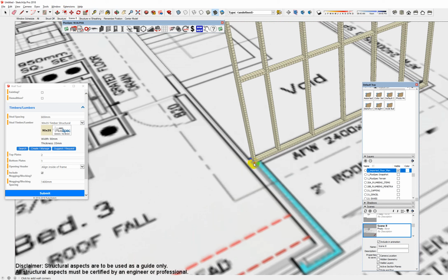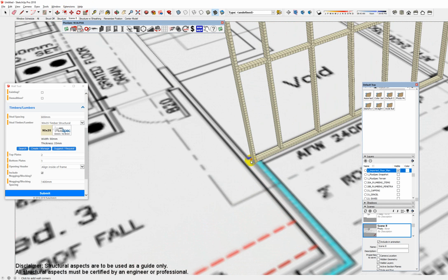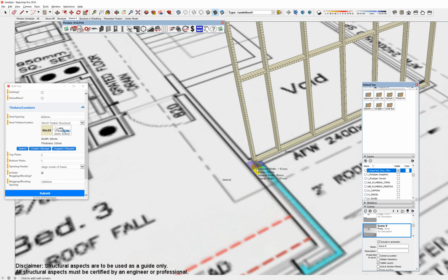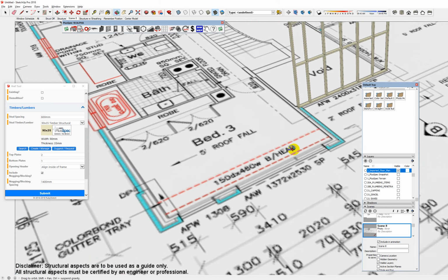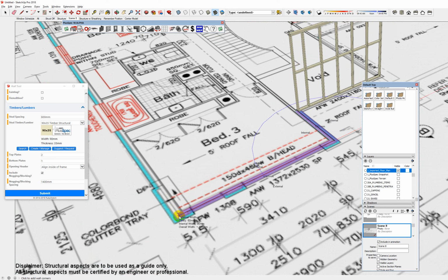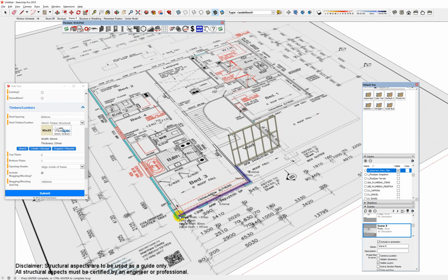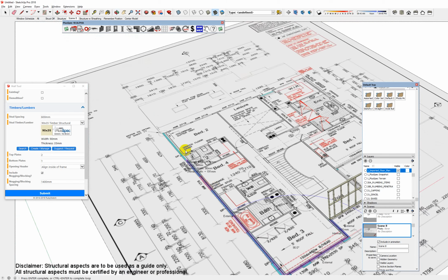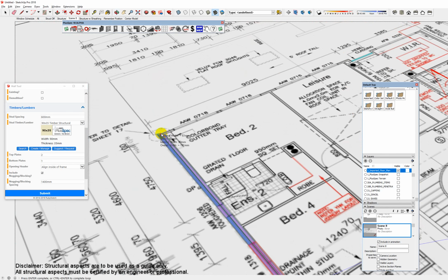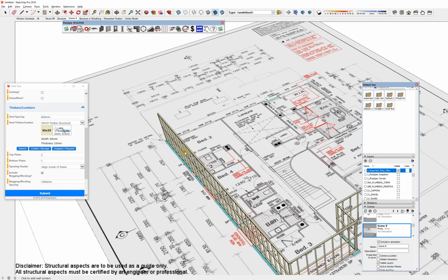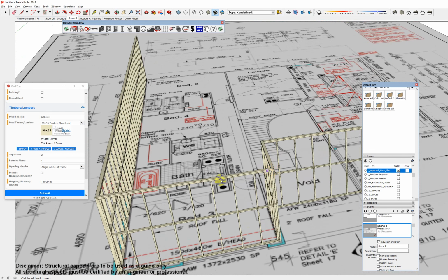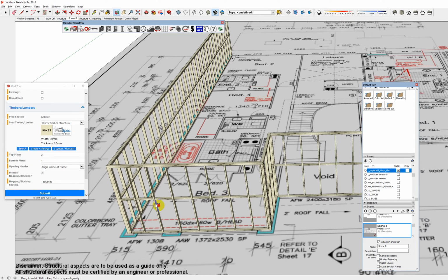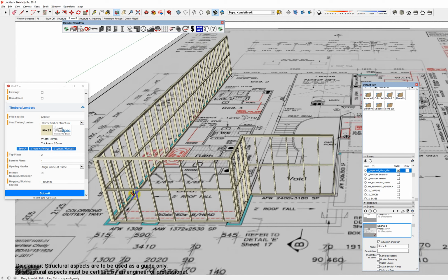And I've just done this wall with a square end on it, okay, because that would be how we'd probably build it in a factory. However, a lot of factories are now starting to miter their corners, and there are advantages to it. I know a lot of people go, no, why would you do that? However, now we're using better quality, better technology saws. We would potentially miter these because it just makes it easier to know the left and right of the wall when you're standing them up. However, whichever way you do it is up to you.